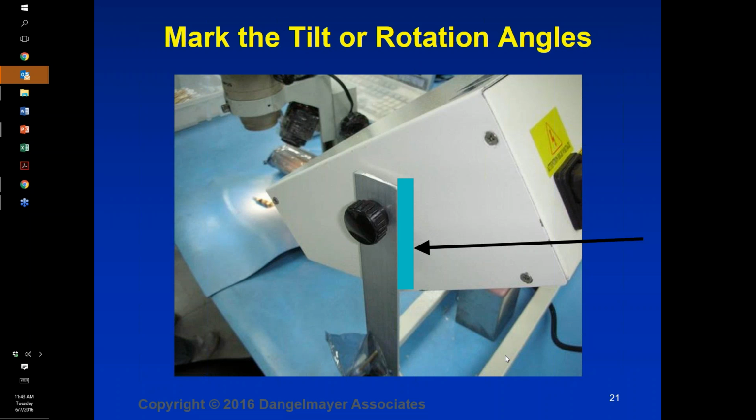Sometimes a visual inspection will tell you. Sometimes the weight of the ionizer will tell you, because AC ionizers work with a high voltage transformer. They tend to be fairly heavy. A DC ionizer will be lighter weight because it uses smaller power supplies. There's a bunch of clues if you had an ionizer in front of you that you could take a look at and probably figure out what type of ionizer it was. But your measurements of offset voltage, certainly if you have a pulse DC ionizer, you'll see that right away because the ionizer will be alternating between positive and negative periodically. So there are a bunch of clues that will give you an insight into what type of ionizer you have there.